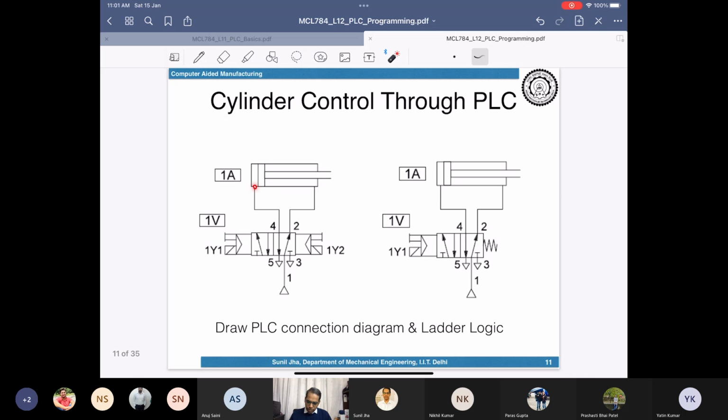Once you make the fluid enter this side of the cylinder, your rod will move forward. And whenever you want to retract it, you make the fluid enter from this side and it will leave from this side. So with the control of the direction of the flow, you will either be extending the cylinder or retracting the cylinder. Now how will we reverse the flow direction? For that we normally use direction control valves. We call them DCVs, direction control valves.